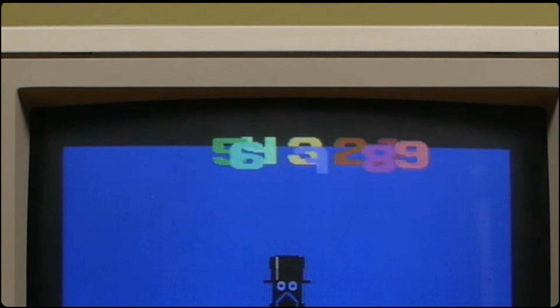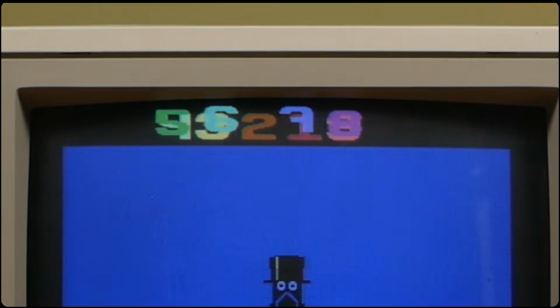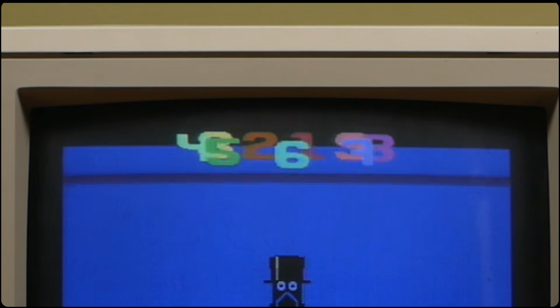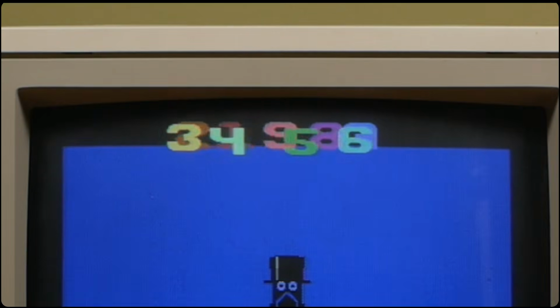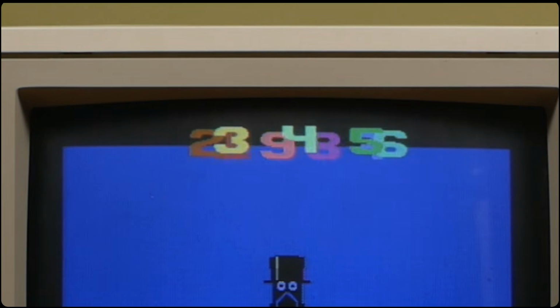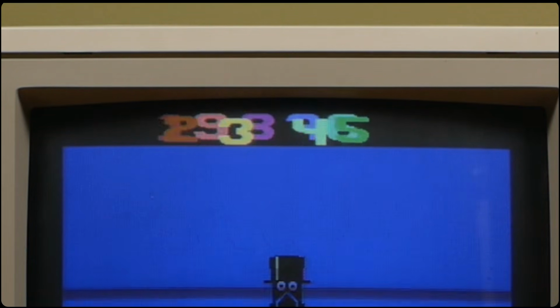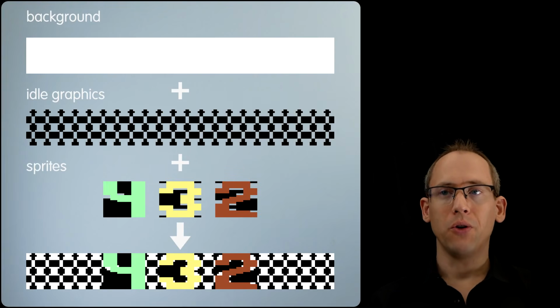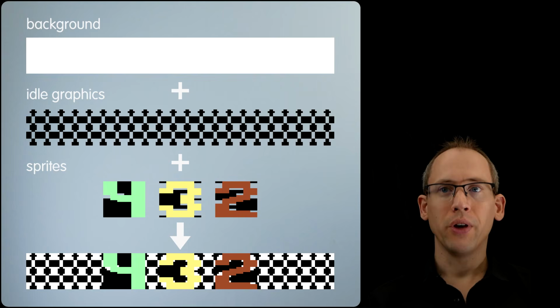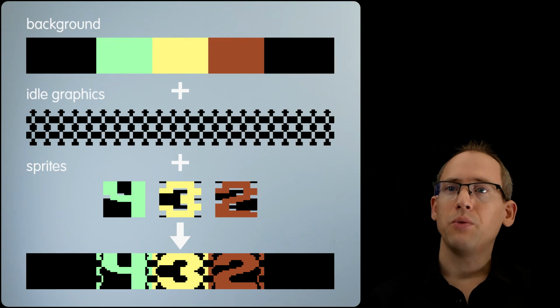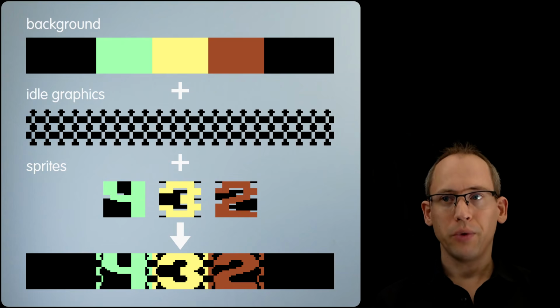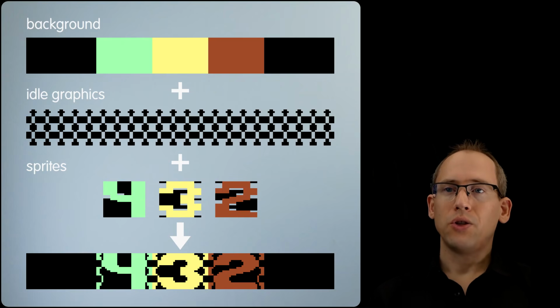And I know the terminology is confusing, we're looking at 9 colorful digits surrounded by black, but technically black is used as a foreground color, both in the sprites and in the ghost byte pattern. So technically, the background color ought to be whatever color the digits have. But here the digits have different colors, so we have to, as the jargon goes, split the background, meaning that we update the background color register as we go, and we do that on every single raster line in time with the video beam. And that's not particularly difficult as such, but there's a twist.